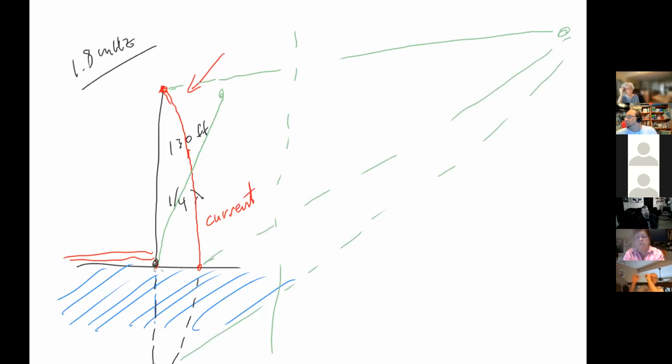So if you have an electrically reflective surface, basically what it does is it creates the image of there being another half of the antenna somewhere else. And then everything is hunky-dory. It makes the world okay. It basically acts like a dipole. The one big difference is that the current that matches it is actually flowing down here in the metallic area.